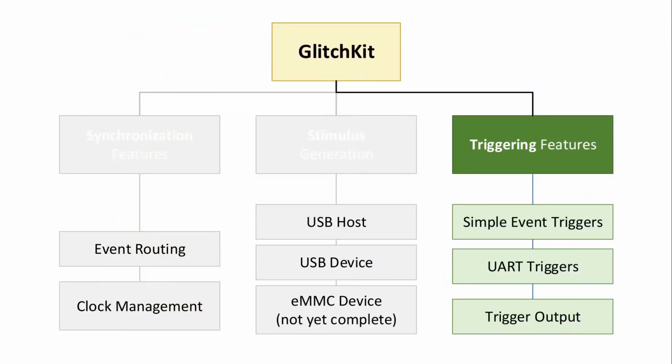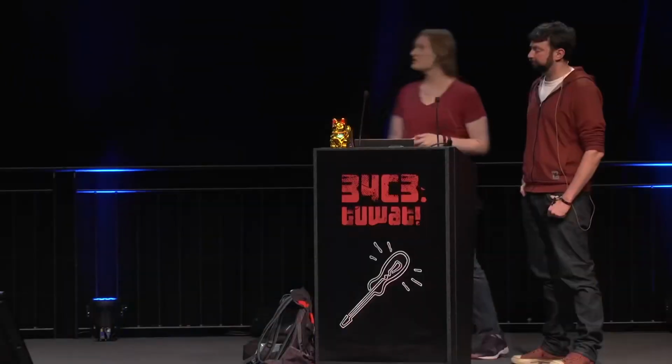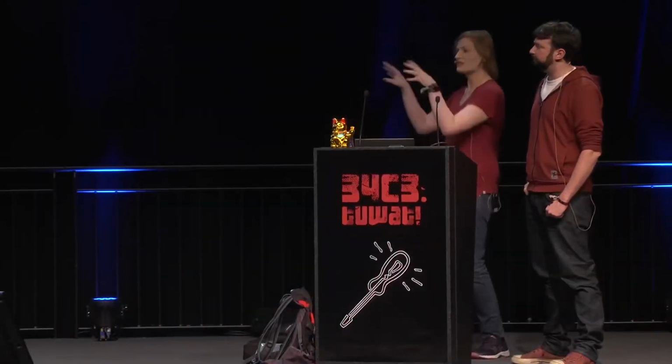Or I could say, okay, I know that this thing behaves the same way every time. The 4th thing it reads is always that piece of information that I'm interested in using as my time base. So let me just say, the 24th clock edge here, or the 30-second clock edge here, while the chip enable pin is low, happens to be the thing that I'm interested in triggering on. And this doesn't necessarily have to be the thing that generates that final glitch trigger.